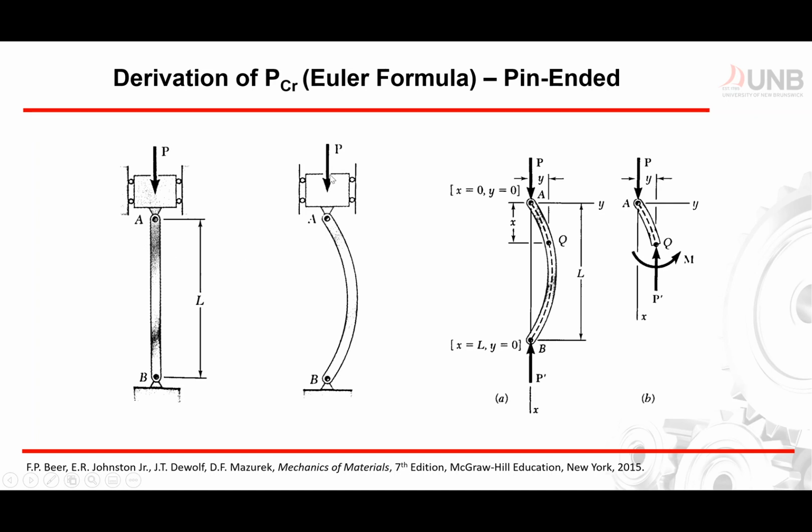We reach a critical amount of P. Your structure starts to buckle, which is the second image here. Now it's buckled. Now after applying a force P, so this is going to be our forces and boundary condition. So we have force P, we have x is equal to 0. So that's our reference point. At x is equal to 0, we don't have any deflection on the left or right side of our column, which means y is equal to 0.